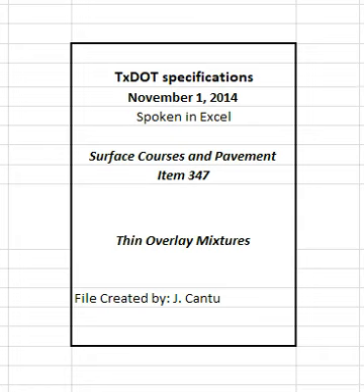4.4.2.1.4 Supplying aggregates. Provide approximately 40 pounds of each aggregate stockpile unless otherwise directed. 4.4.2.1.5 Supplying asphalt. Provide at least 1 gal of the asphalt material and sufficient quantities of any additives proposed for use.